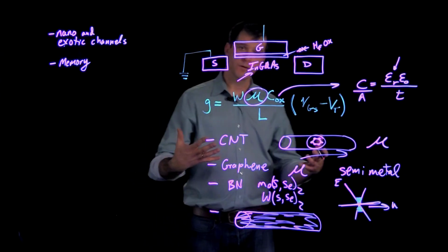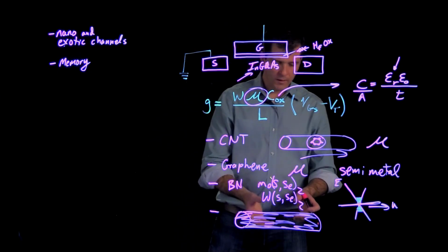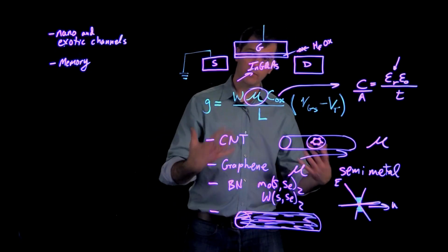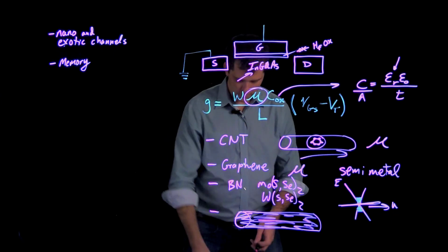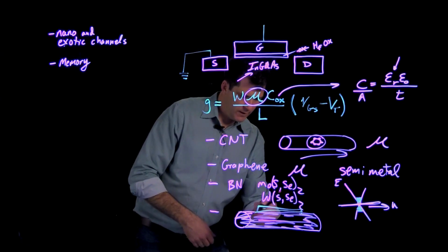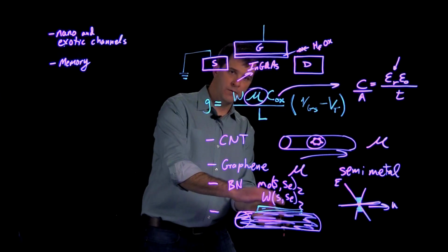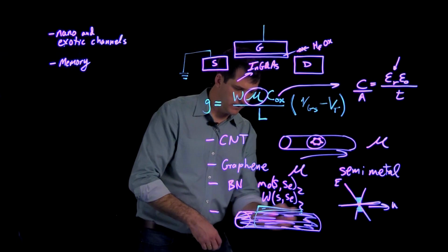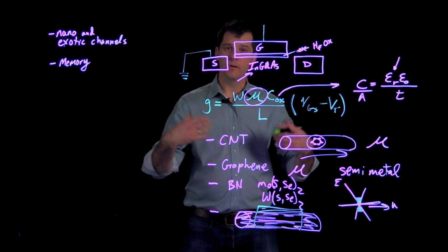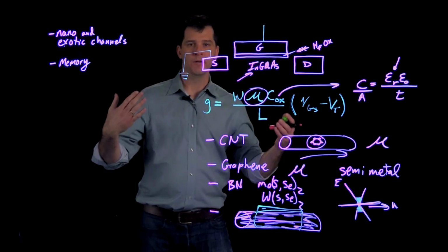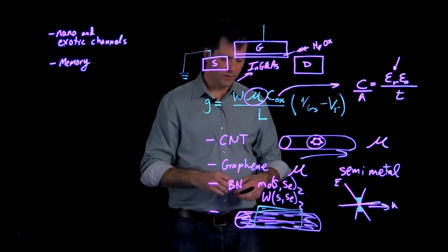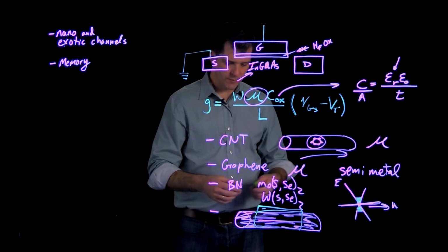And the benefit to using a material like this would be, one, in terms of its large mobility in plane because it's made of a compound semiconductor, but then two, because if you put a gate on top of it, the actual physical dimension of this nano object is very small, and so you get very nice charge control over the entire volume under the gate. And so the switching ratio between the on and off states can be very high in a very small volume.